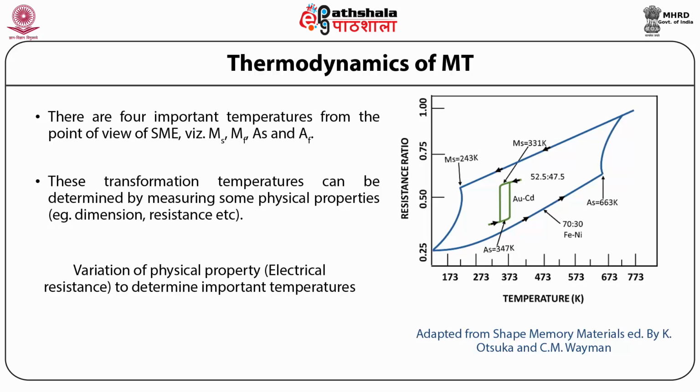As discussed earlier, when the transformation zone is small, the driving force is also small, and hence the process is reversible, which is also called thermoelastic.